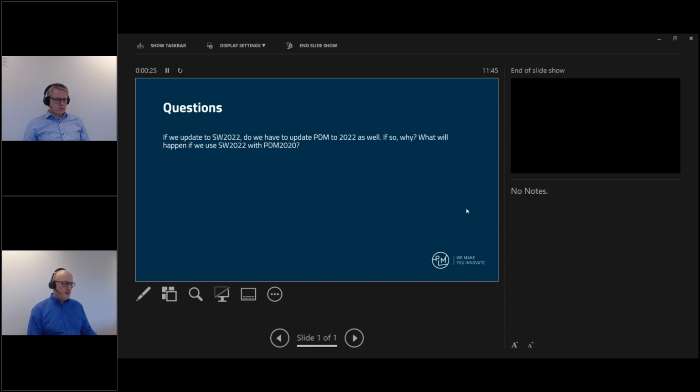The thing with PDM and SOLIDWORKS is that if you have SOLIDWORKS 2022, you have to have PDM 2022 as well, or a newer version of PDM. The PDM system cannot be older than the year version of the SOLIDWORKS installation, basically. And that is decided by SOLIDWORKS. So that's just the way it is.